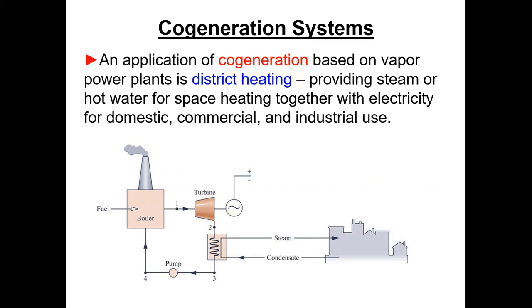But anyway, that little town got a lot of its space heating from the aluminum plant that had a big boiler. They would bring hot condensate back, and circulate the heat through a heat exchanger. They would heat some water, and pump that water all around town. And the residents would take that hot water, and that's what would heat their homes. So that was a perfect example of district heating.